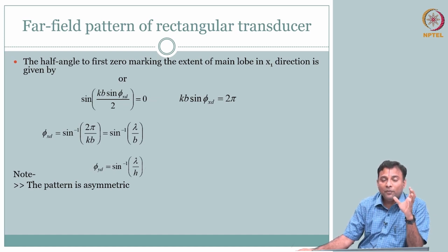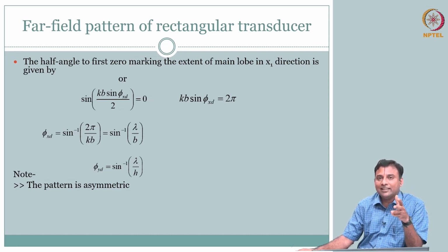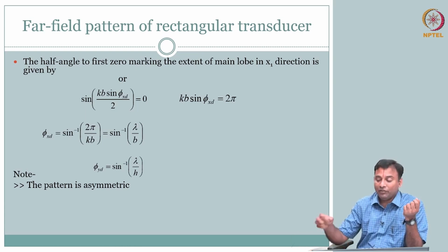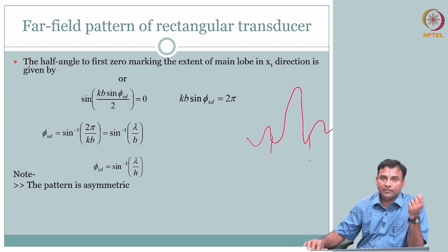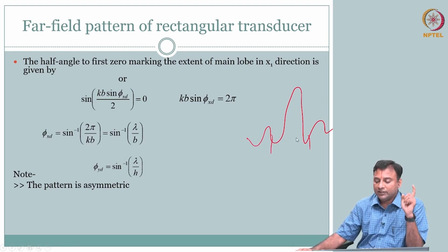So, something that I probably missed. Circular is also the same: when I said rectangular, you got sinc. When I have a circular disc, the Fourier transform of that is a Bessel function, which also has a standard form. So, you can calculate the zeros; the first zero crossing in your Bessel function you can define as your main lobe. That is how it was done there, but it was circularly symmetric, so I forgot to mention that. Here it is not symmetric.